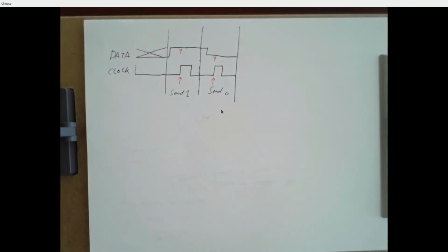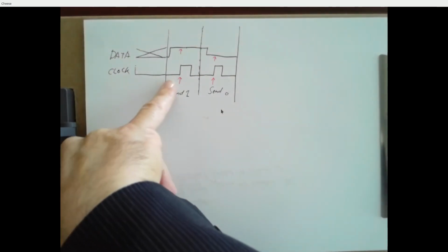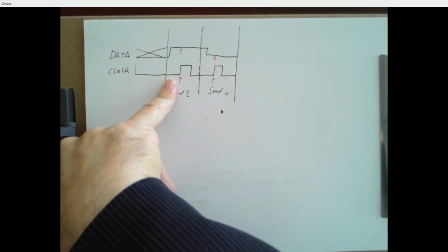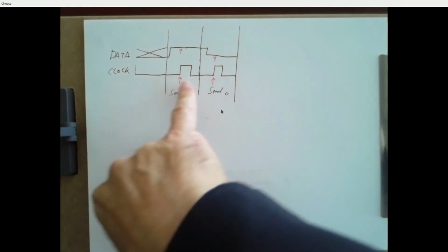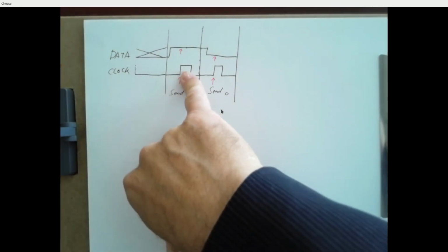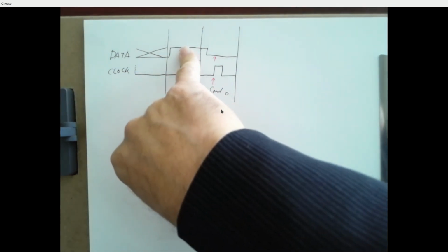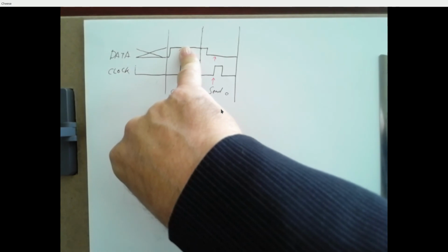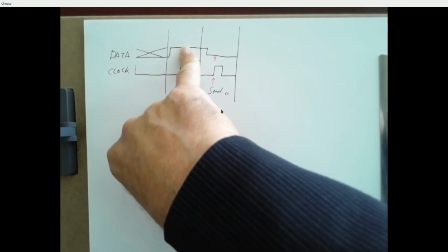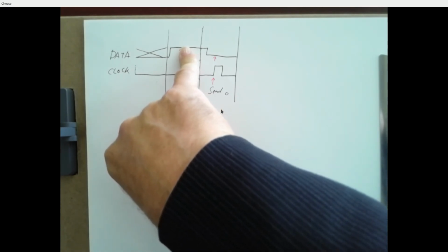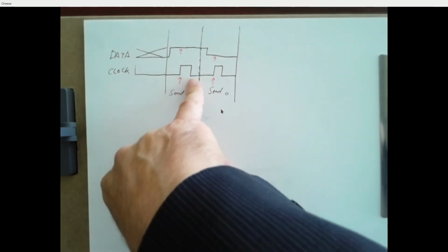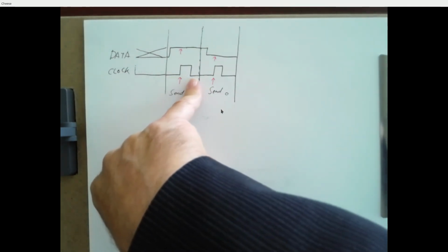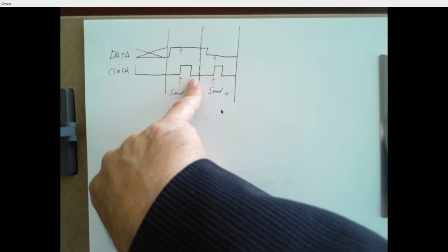That's what you did with your switch, lab 4. So you read the clock line, and you should be normally reading a 0. The first time you read the clock and you see a 1, immediately go and read the data. And if you see a 1, you're being sent a 1. If you see a 0, you're being sent a 0. And then don't do anything until the clock goes back to a 0. And then go back and do this all again.